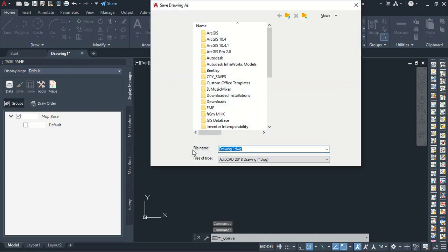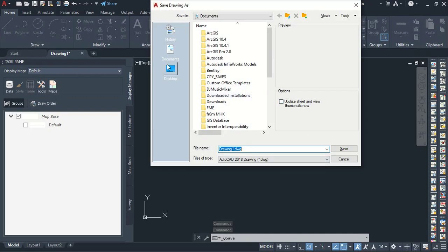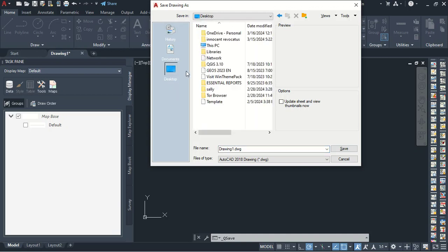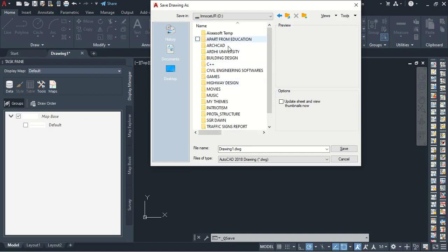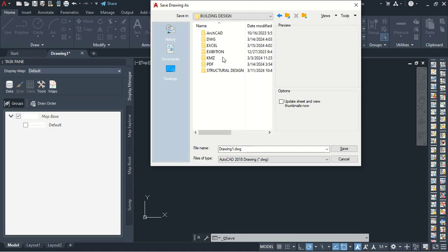So we are going to create the following layers, and we are going to follow these settings, because these settings are the ones that I have been relying on to create some layouts which are nice looking and structurally accepted. So the first layer, we are going to create the grid line. We are going also to create the beam layer, the column layer, the bubbles, and I'll explain what this is, the text, and also the dimension and the layer for the staircase.